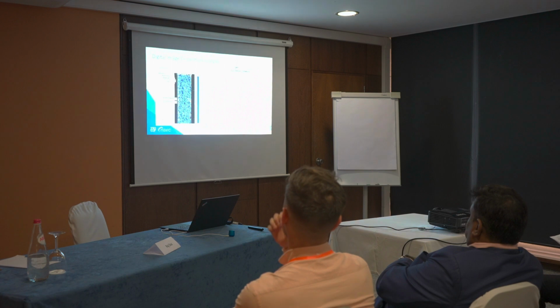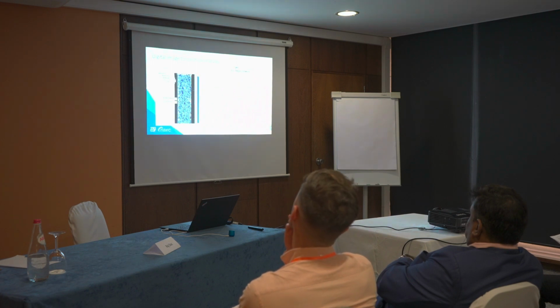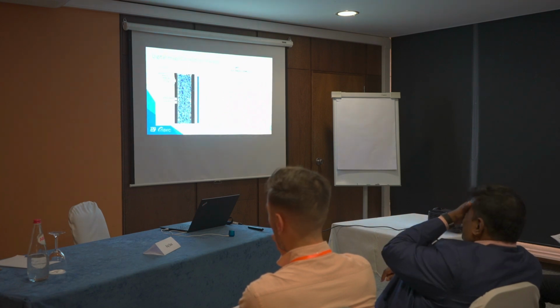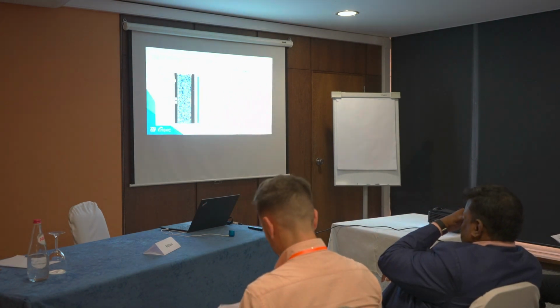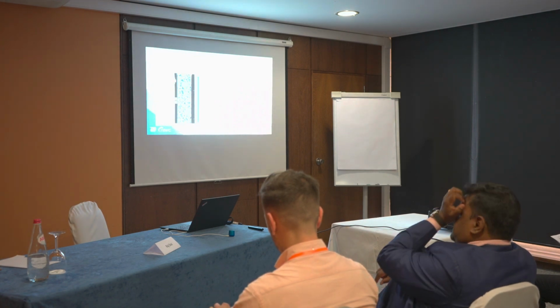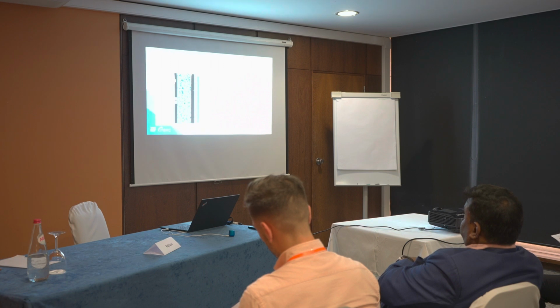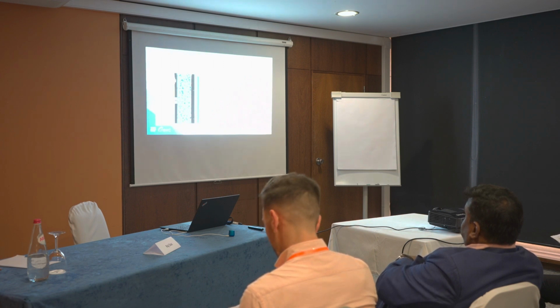We utilize digital image correlation to analyze the results which we gathered from the experiment, since it's difficult to use the traditional strain gauge approach to measure the strain in this experiment. So we utilize the speckle patterns and a camera, analyzed in the GOM software to obtain the strain.